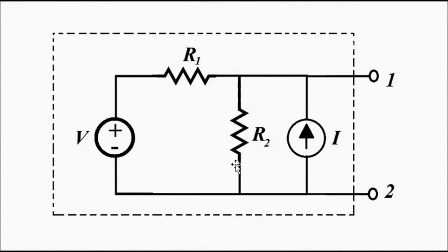Suppose we want to determine the Thevenin equivalent of this circuit network across R2. For that we have to remove R2, open circuit it, find the VTH, the voltage across these 2 points, then RTH. Same, we can determine the Thevenin equivalent in a circuit network across any 2 points, across R1, these 2 points across R1. For that we have to open circuit it first, VTH, then RTH.